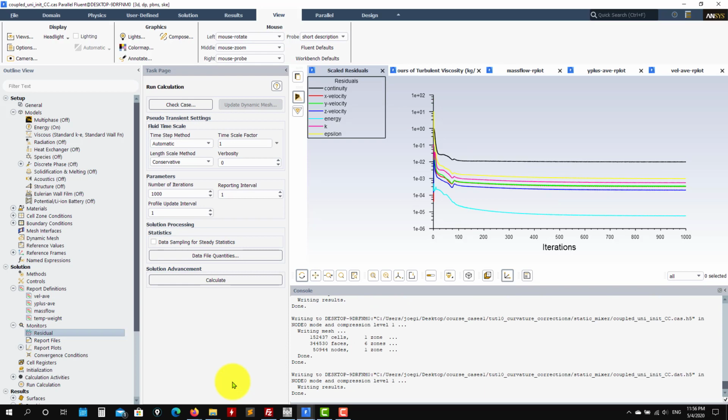So now this is the coupled solver, okay? This is the one that I highly recommend to use, but it's not always the best solver. In some cases it might be better to go to SIMPLE or SIMPLEC or PISO. As you run this case and measure the cost per iteration, you will realize that the coupled solver is very costly per iteration. It costs much more, but we're going to see that you might reach a stable solution much faster.